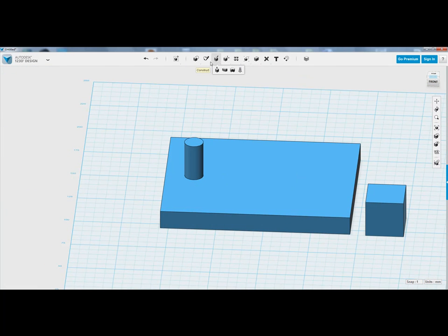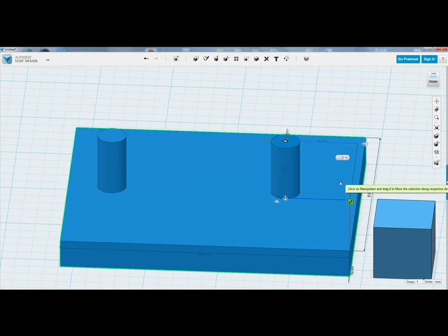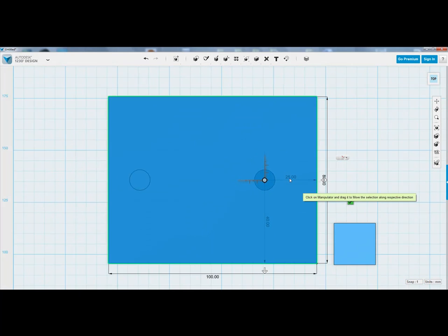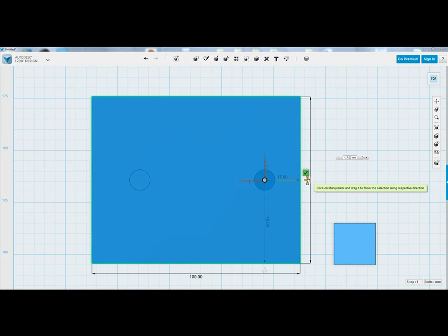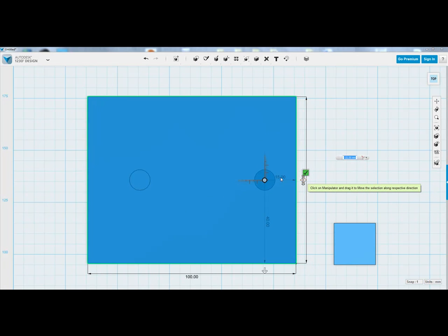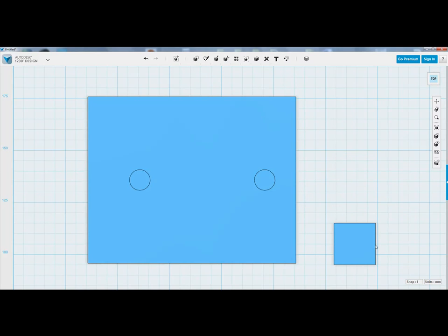I'll do that again one more time. I can copy and paste that. Press enter. So if I get my ruler, find my center point, click on my form, go to my top view on my view cube. That is 25 from the edge at the minute. You can then move that to where you need it to be. So hopefully that helps. Have a go for yourself.